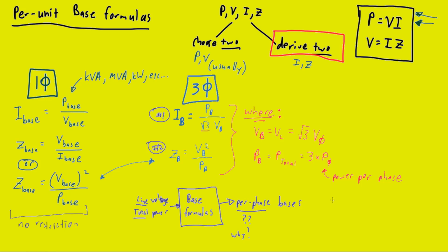Well, in balanced three-phase circuit analysis, what we actually end up doing is treating it like it is 3 individual single-phase circuits. So what you have in your circuit analysis is, in a sense, per phase voltage and 1/3 of the power being demonstrated, but you have it demonstrated 3 times essentially.